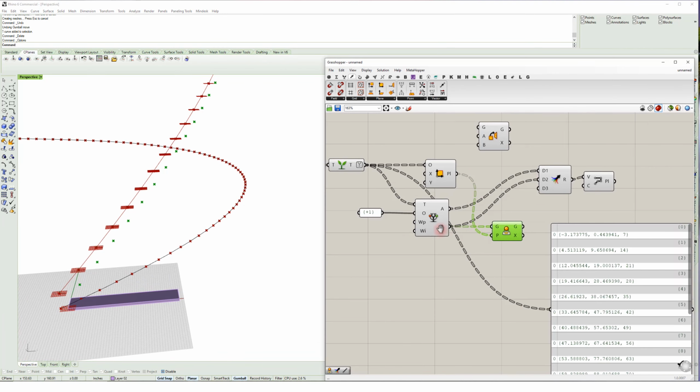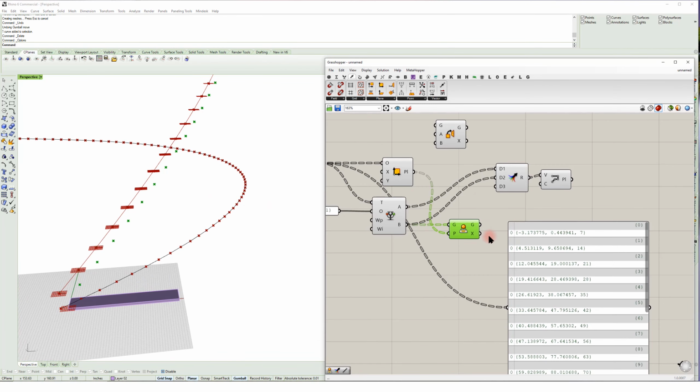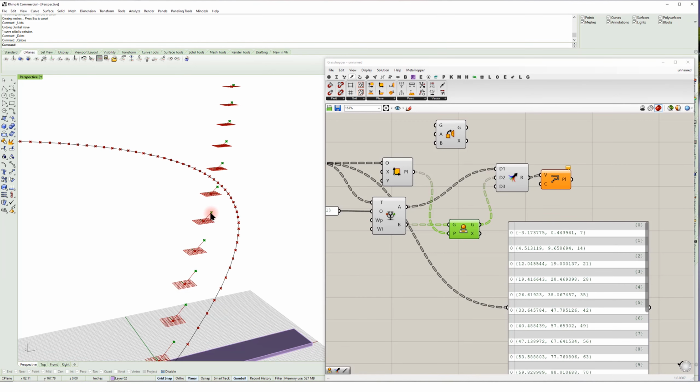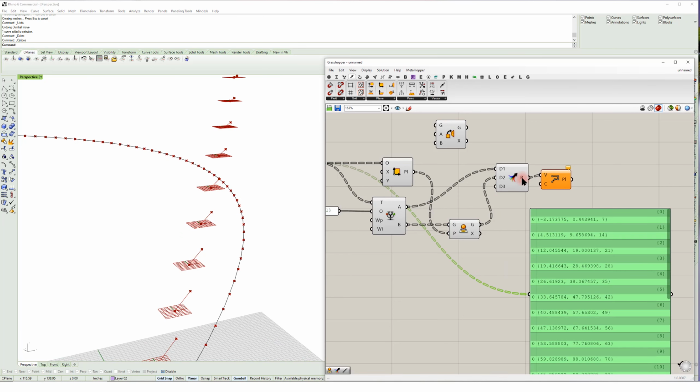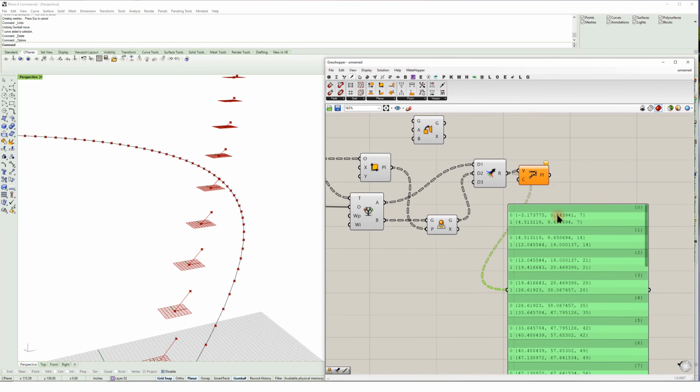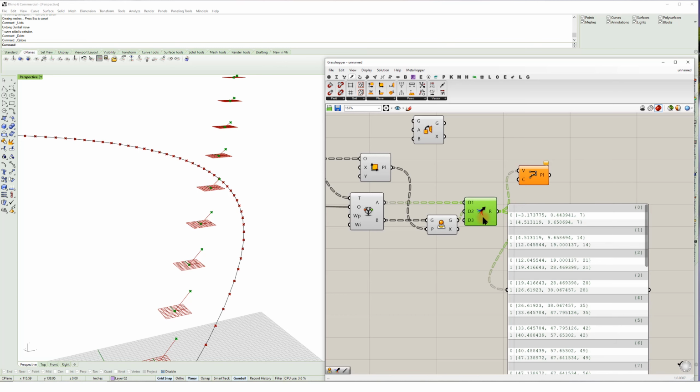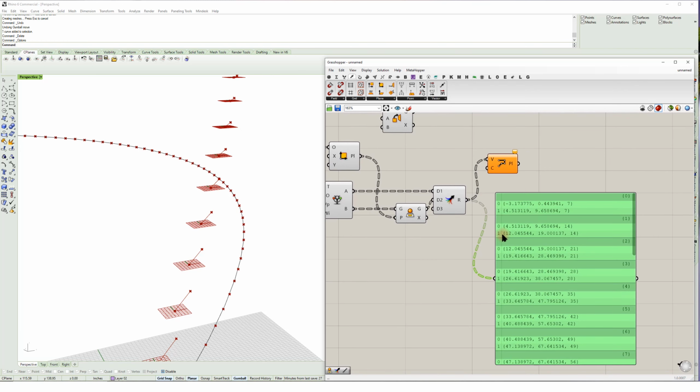So what is that doing? If I take my newly projected point and plug that into the B, that's actually grouping it. You can see here, it's grouping it on its own branch. So when I've got each of these branches plugging into my polyline, that's giving me those 2 points. So it's taking this point from up here, projecting it down onto that plane.